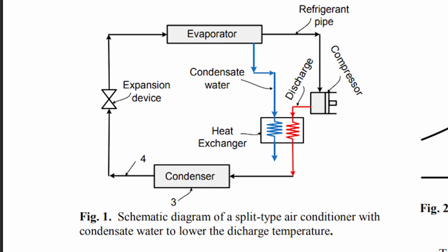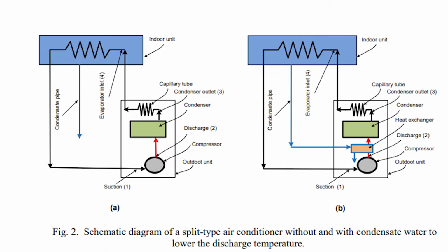I'm going to explain about the schematic diagram of this journal. Okay, this process begins when the compressor starts working, compressing the gas tightly to increase the pressure and the temperature of the gas vapor. Then this gas vapor will go to the condenser through the connecting pipe. In the condenser, the high pressure and temperature gas vapor will change from gas to liquid at the same temperature. This means the temperature will remain the same, but the condenser will change the physical state from gas to